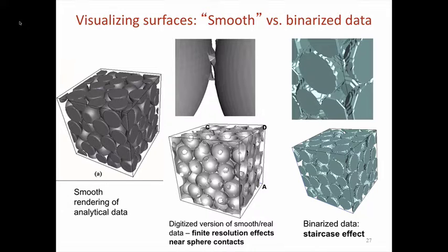So you might have some funny looking triangles there around that contact area. That's all fine. Okay? It's not a big deal. It's plus or minus 1 voxel around that contact. So when you're trying to precisely resolve your surfaces, because of numerical issues, you might get a little bit of finite resolution effects. So just a warning out there.